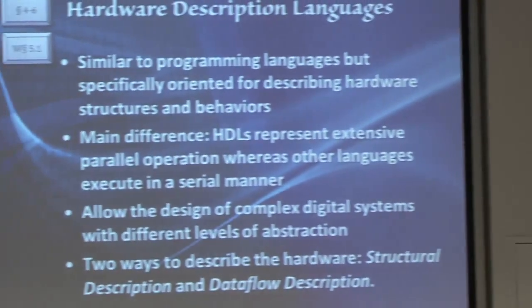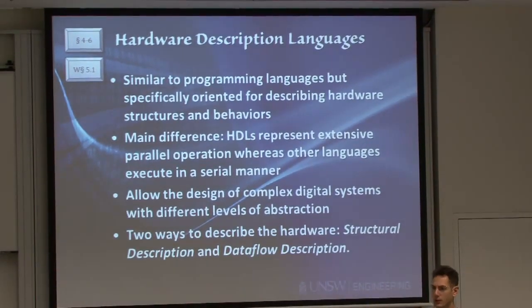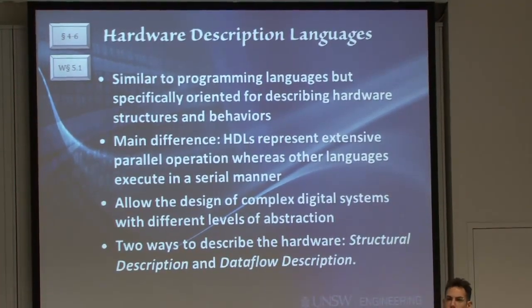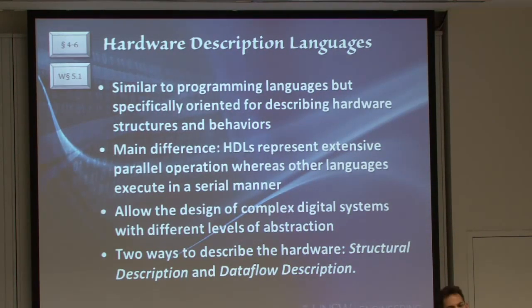Now, there's a huge difference between HDLs in general. HDLs, again, hardware description languages. There are a few of them out there on the market. We're going to talk about the Verilog HDL. I will mention VHDL, which is another one. There are a couple of others as well. But what's common to all those HDLs, and distinguishes them from regular programming languages, is that when you write a program, say in C or any other programming language, your commands are executed one after the other, in a serial manner. You execute one instruction, you finish processing it, you move on to the next one.